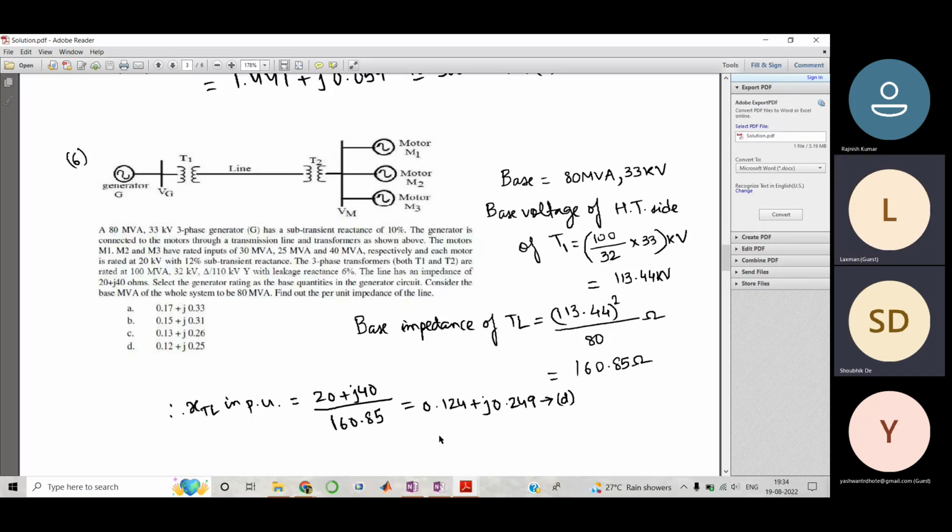Yeah, as far as I know, this transmission line has a certain distance, so the reactance as well as the resistance changes with the distance. With a fixed distance, it will have some fixed impedance. So I think it is always given in ohm and not in percentage. Okay, but in that case, they could have represented it in per unit per kilometer value. We can, but if they mention the line length directly, it becomes a bit complex, because you have to again multiply it with the distance, an extra step. Okay, thank you.